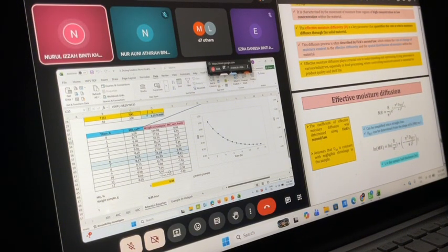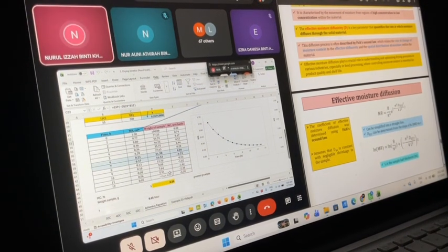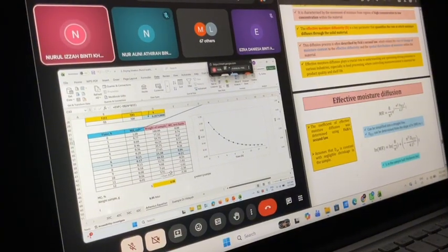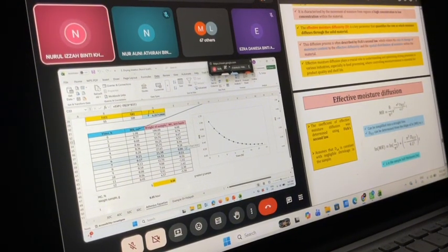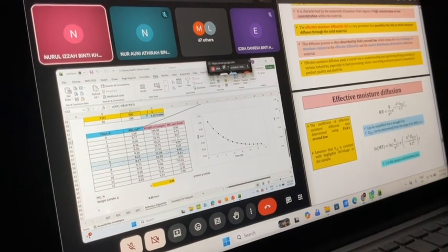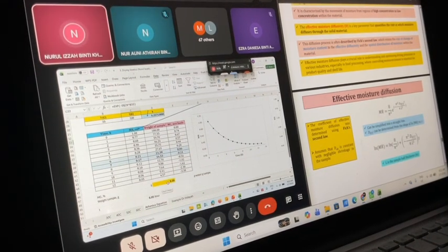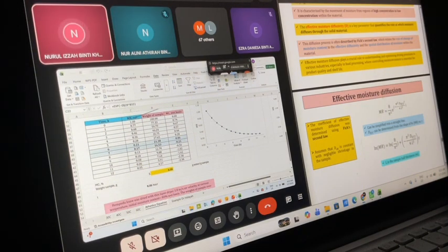After that, you can know, because the question asks you what is the drying time needed for the moisture to be 0.05 on a wet basis. So the question asks you at 0.05. You have plotted this table for 55 degrees C. So what is the drying time needed at 55 degrees C to reach 0.05? You can see that the value is between 0.06 and 0.21 here. So you do the interpolation.